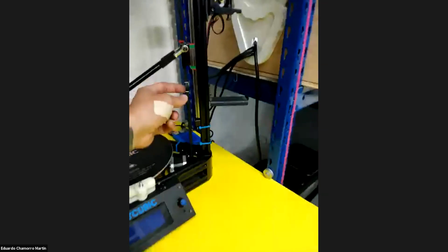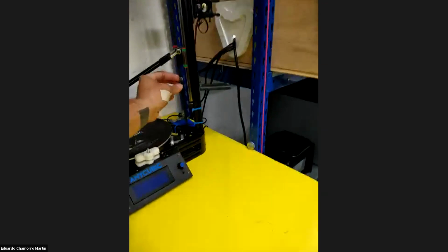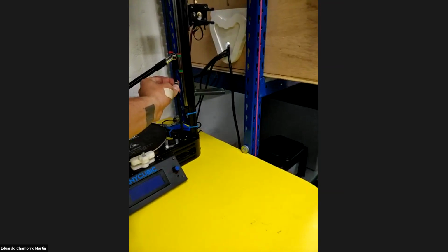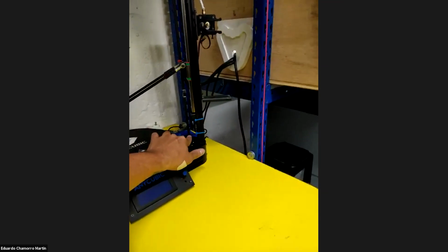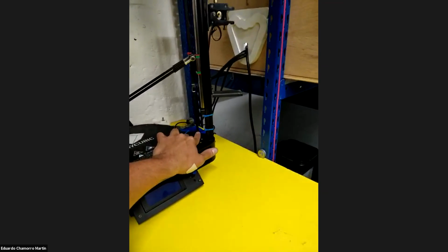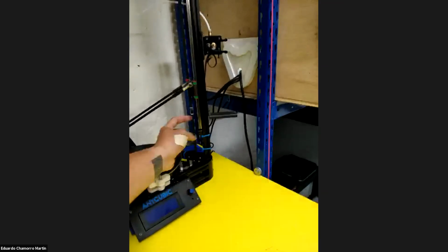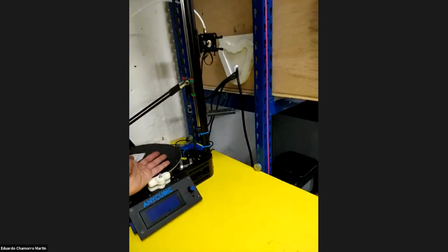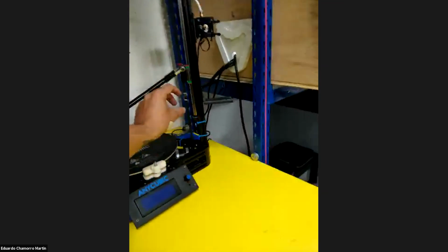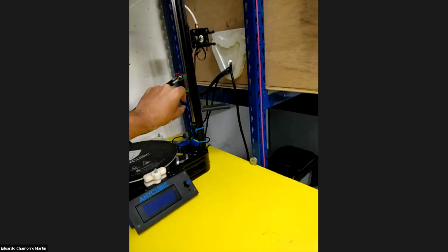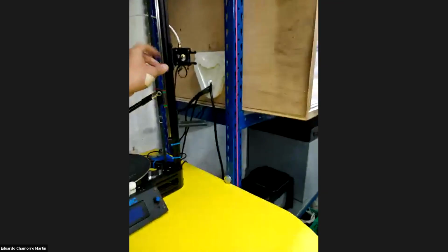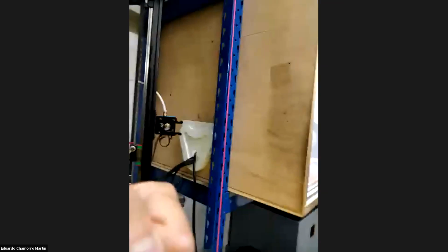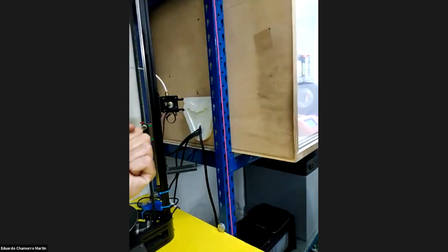And you see this little tension, this is a spring. Ideally, we should not have this, but it helps a lot for keeping the belt in tension. Ideally, you should have a secondary system that is a ball that pushes the belt a little bit eccentrically. The cheap solution, and it works well for 3D printers because they don't have a lot of mass, is a spring that is quite strong to keep the belt in tension. What happens if you pull a lot? Let's say you use this for milling, making a lot of force, the spring elongates. That will not be good. For example, this is not a solution you could use for something that you need to push with.